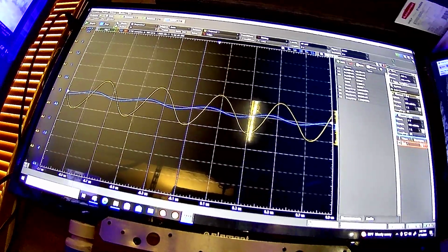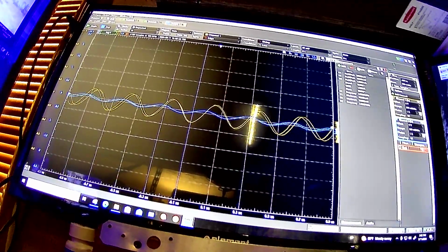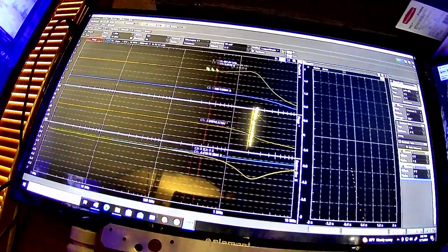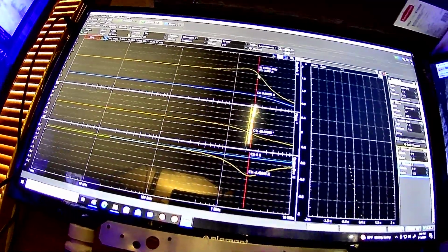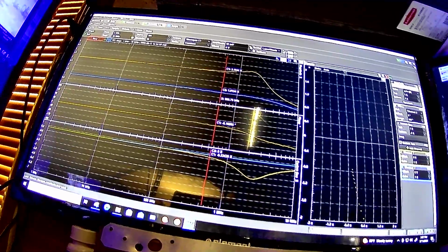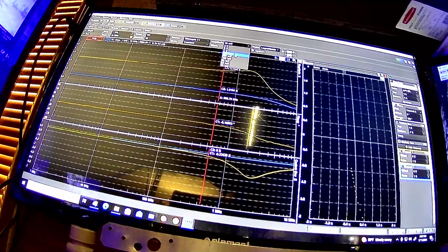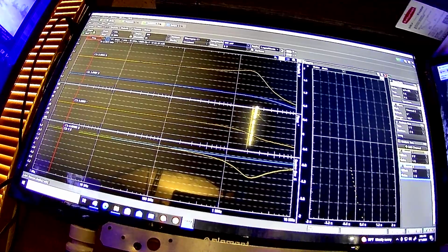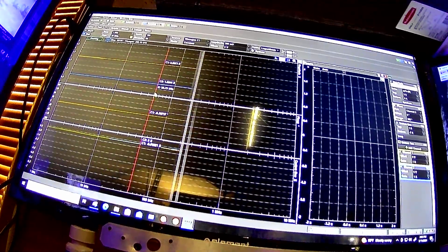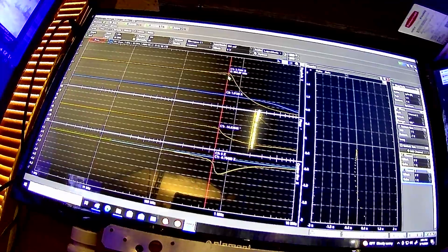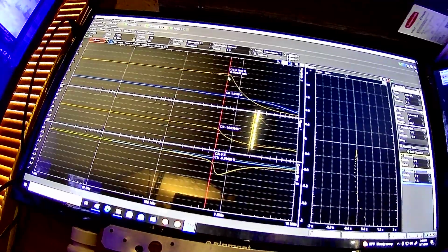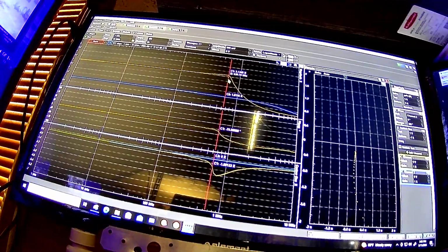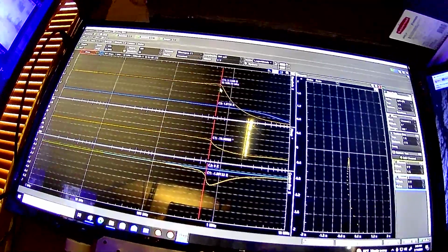But anyway, I just thought I would go into that, to show you what the kind of output profile of this thing is with a gain of 3. You can kind of test this at higher voltages too. I can put like 500 millivolts, but you'll lose your gain typically. But see, the hump is greatly reduced now, at a 500 millivolt signal, but we're still getting a gain of 3 out in general. But the hump is not as prominent anymore, but it's definitely happening at a lower frequency.